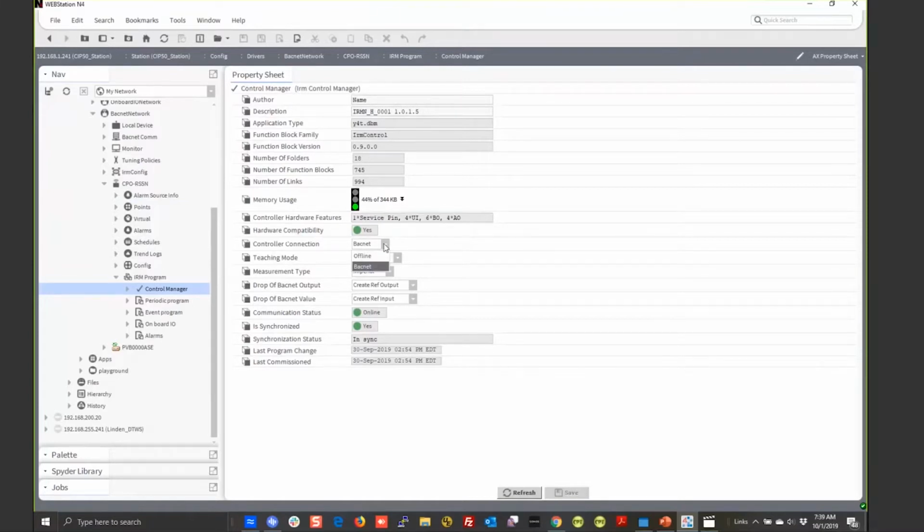If you're working with it offline or on the BACnet network, this is that teaching mode, immediate or on demand. This one I didn't find till late yesterday. I couldn't figure out why everything was coming through as Celsius, and I was changing the scaling to linear and then using the 1.8 and 32 offset to make it work. Oh, there it is. So you've got your imperial, so that obviously makes it easier.